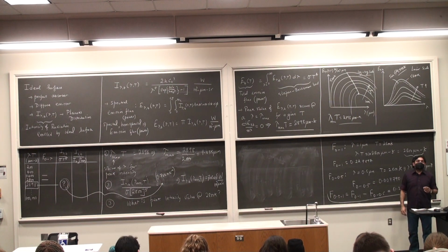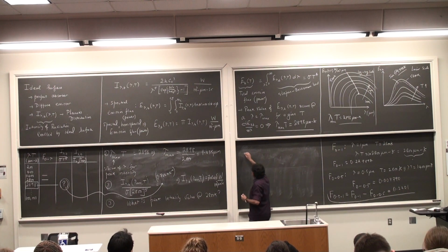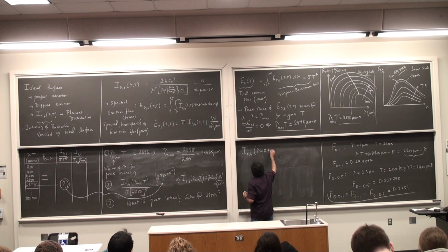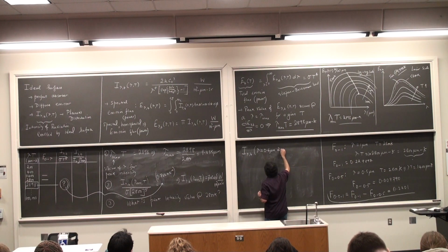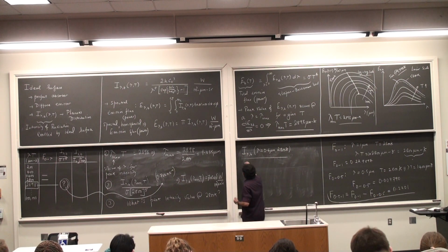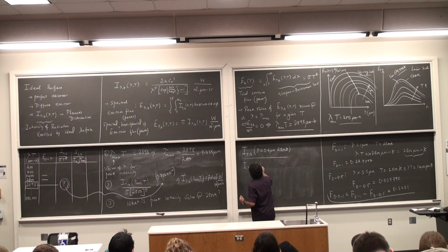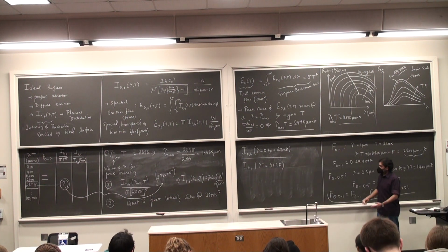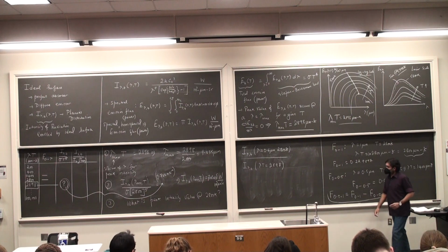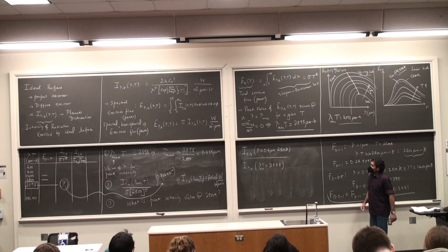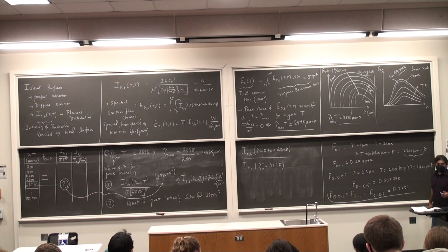I want to find relative intensity at a particular wavelength. So I lambda comma B at lambda equal to 0.6 micrometer and 2800 Kelvin, divided by I of lambda comma B at lambda T equal to 2898. That is the peak value, or lambda max value, whatever that is. This is lambda max, which is the value that we just calculated. So multiple ways of doing this. The easiest way is to use the table.